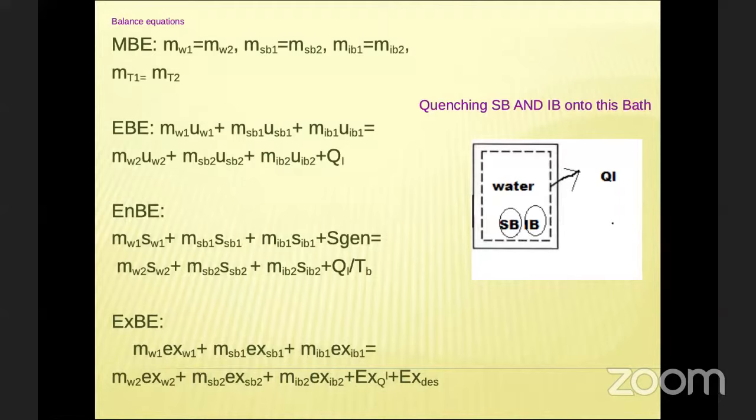If you look at all the equations, nowhere am I using the dot symbol. Normally in thermal engineering, when you put a dot, in terms of kilogram per second, flow will be there. That is only in the open systems that we are going to discuss next. Right, so open systems. What is the meaning of open system? There will be a mass flow rate and energy. Mass flow rate means we are not going to use m, we will be using m dot, right? So mass also is crossing the boundary.